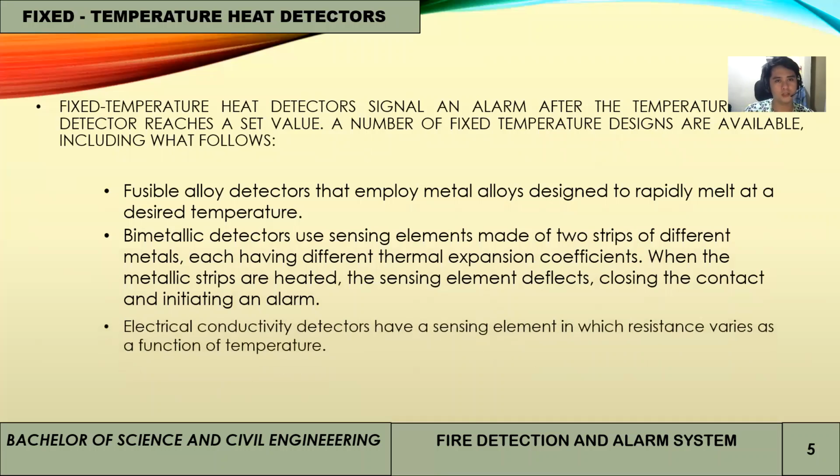Fixed temperature heat detectors. Fixed temperature heat detectors signal an alarm after the detector reaches a set value, and a number of temperature designs are included as follows. Fusible alloy detectors that employ a metal alloy designed to rapidly melt at a desired temperature.